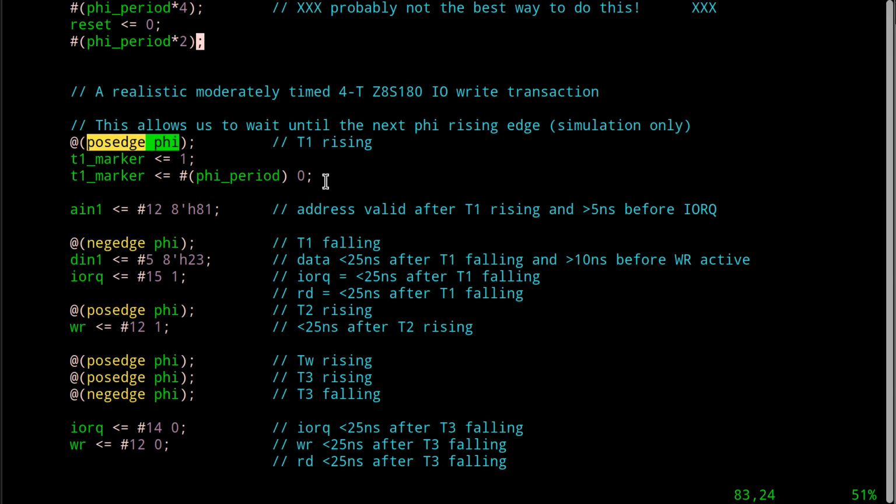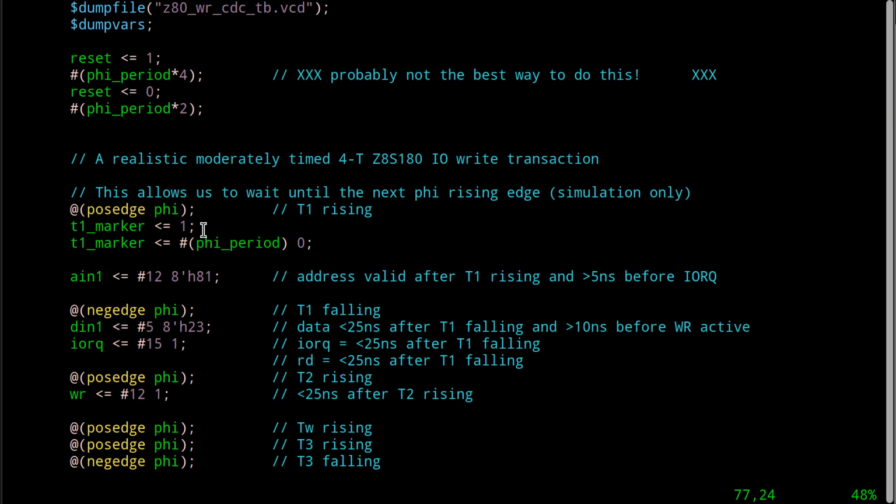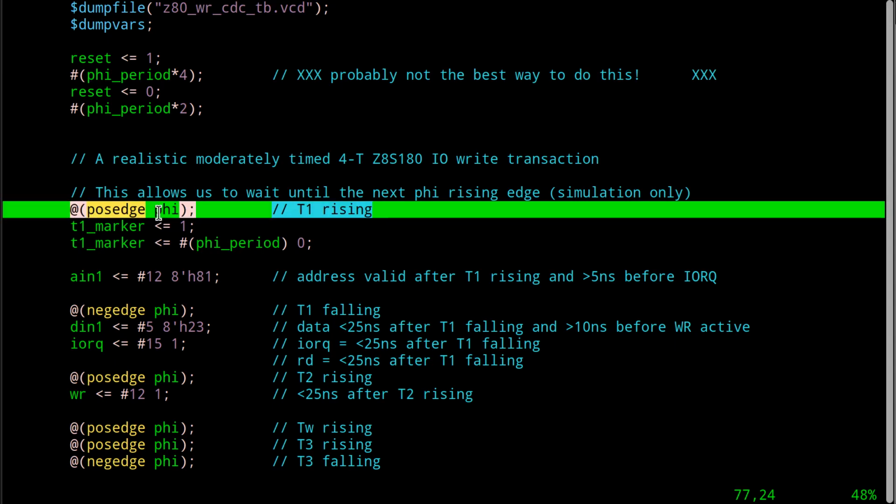When you use them in your synchronous circuits that are in the always block, you always at, when you give it a clock and stuff like that. Well, you can use them right in line like this. You can't do this, obviously, in synthesized code, but in simulated code, what this means is wait until this happens.